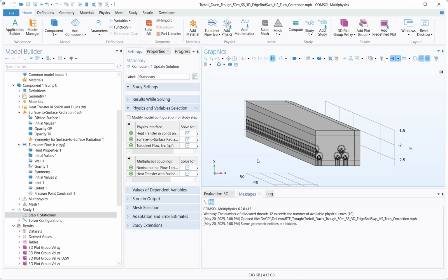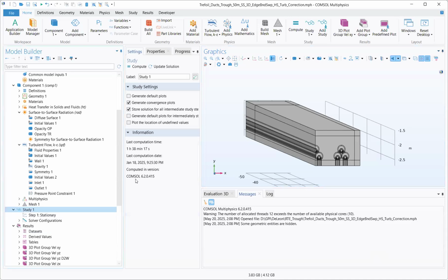And since then, it's been about a year or so, I trust steady state thermal simulations, but I didn't in the past. So some of these things were done longer than a year ago, when transients were done. Some others, we just do the steady state. And it is advantageous to do a steady state, stationary solver. If the customer or anybody is interested in steady state, and if it's not necessary to do time dependent, then don't do time dependent, right? If steady state is all that is required.